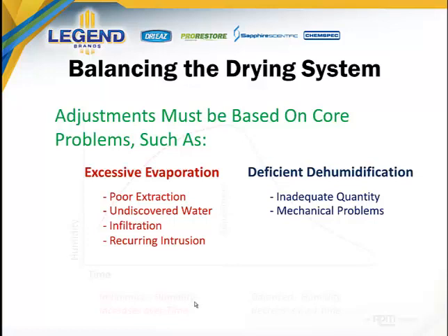One of the major causes for a high humidity spike, in other words, is not that you haven't installed enough dehumidification, but the dehumidification you've installed is not performing to spec. The common causes for this are inappropriate filter management, coil systems that have not been cleaned for a good number of years. Now, these are inspections that should be performed on a regular basis on dehumidification equipment.